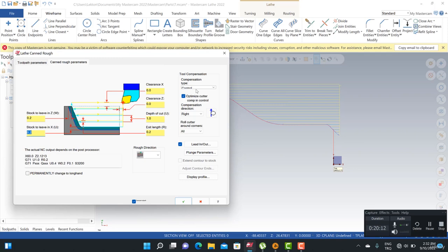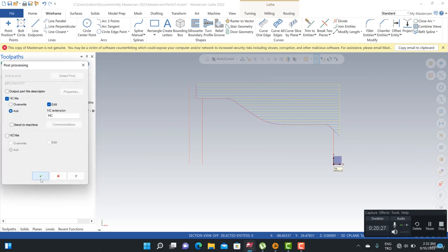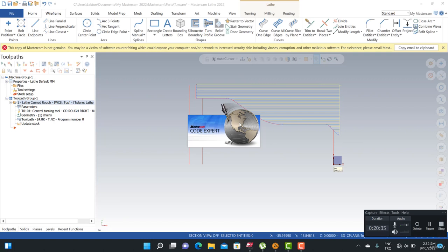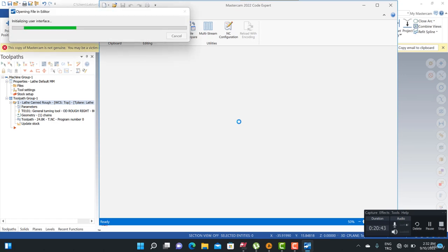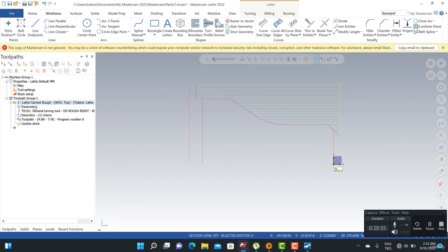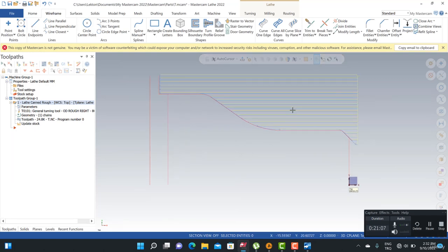Actually, most of the time I prefer to use the computer, because I think that calculation is better. I prefer to use that one. If you intend to change your profile, you need to turn back to your Mastercam as well. But if you intend to change your profile between the blocks, it's also possible. You can easily change it on your CNC, but at that point you should use the control options, because my compensation type is calculated automatically according to my radius.